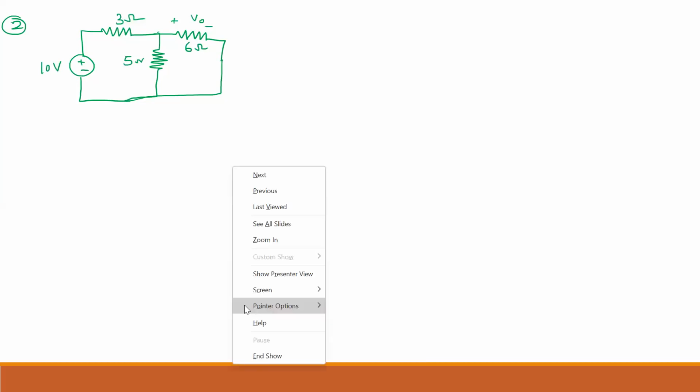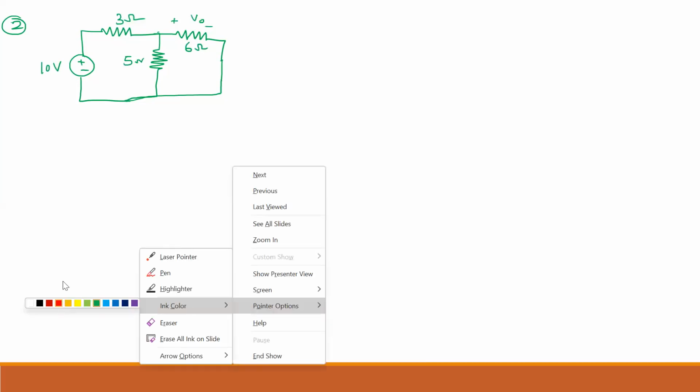Now you have to see whether any practical voltage source or practical current source is there. In this one only a voltage source is there. So practical or not, you have to check. How do you check? If there is any series resistor, yes, then it is practical. Yes, in this problem the given resistor and the voltage source combination is a practical voltage source. So now you draw it separately.